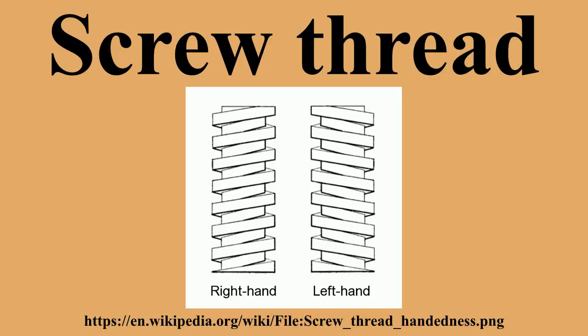Diameters. There are three characteristic diameters of threads: major diameter, minor diameter, and pitch diameter. Industry standards specify minimum and maximum limits for each of these for all recognized thread sizes. The minimum limits for external and the maximum limits for internal thread sizes are there to ensure that threads do not strip at the tensile strength limits for the parent material.